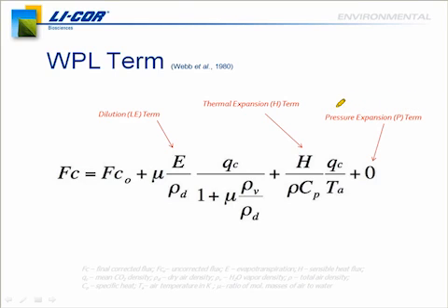Many pumps used for eddy covariance are either diaphragm or rotary vane pumps. Now, especially with diaphragm pumps, the up and down motion of the diaphragm can create small pressure perturbations. So sometimes people will use a buffer volume before the pump, and that helps dampen some of those fluctuations, but that's not always the case.